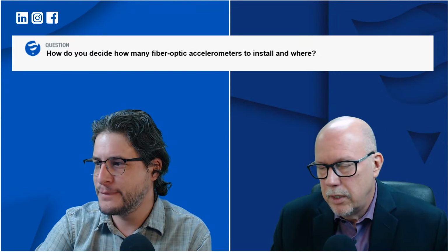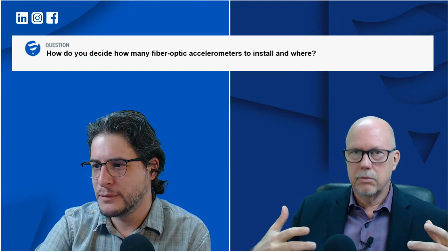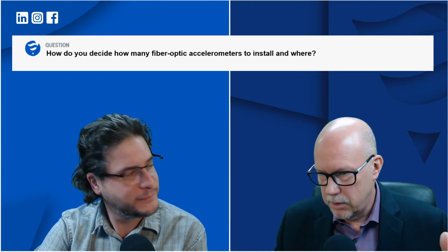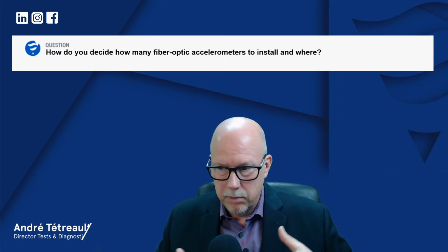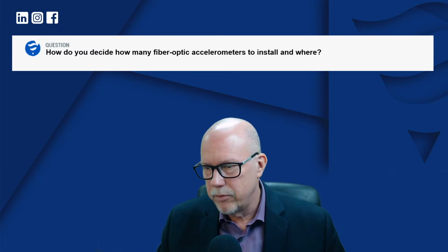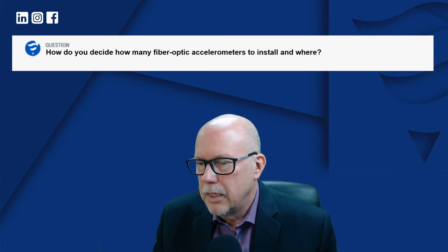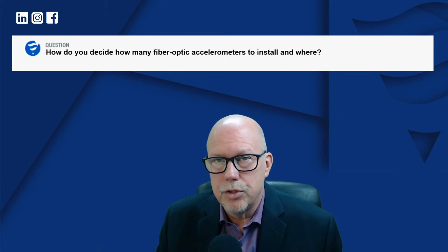Someone else had a vibration-related question. He wanted to know, how do you decide how many fiber-optic accelerometers to install, and also where to install them? Well, that's also a question we get quite often, and it's a very valid question. My initial answer as an analyst, and of course I've never actually bought any of this equipment, so budget is not a concern for me, would be: you put sensors everywhere. As many as you can. But of course that's not practical. Budget is always an issue.